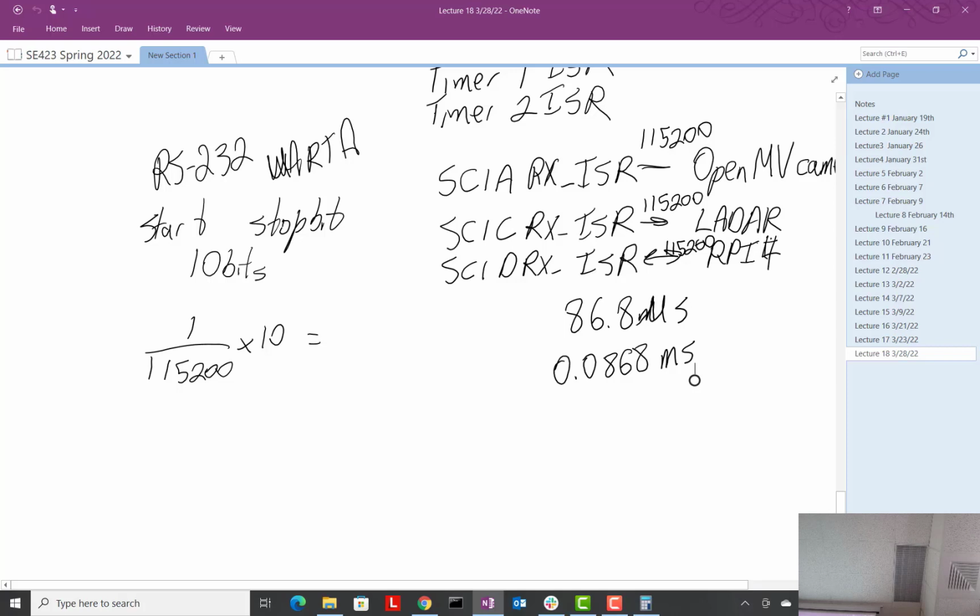Code that takes, say, no more than, let's say, 400 microseconds to run. We'll throw that number out there. Something like that. How would you know? The only way to know is by doing the timing with the logic analyzer. Anyway.